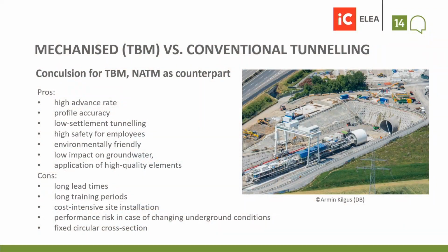From my personal experience, if it's possible to design a TBM, go for it. It's the better one, due to the fact that there are many pros, such as the high advance rate, the good profile accuracy, which leads to less muck amount, then the lower settlements, the higher safety for workers, and of course also its environmental friendliness and low impact on groundwater. Due to the high quality of the precast elements, we can produce a high quality tunnel which comes with good durability properties. But there are some points where it is definitely not recommended to design a TBM drive.